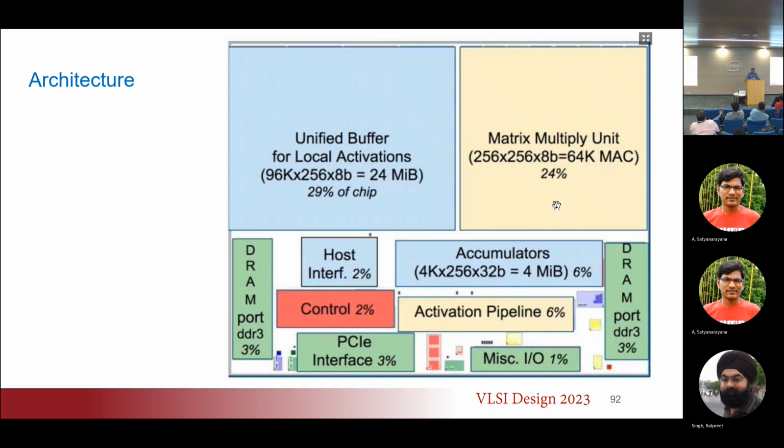This, by the way, is what everybody does, which is the input and the data widths are different, and the multiplier size is different, and the accumulator size is different. And so in CUDA programming, they already have data types where you can specify what type of data you want to use, and people are always using different sizes for the accumulator and different sizes for the multiplication result and your inputs.